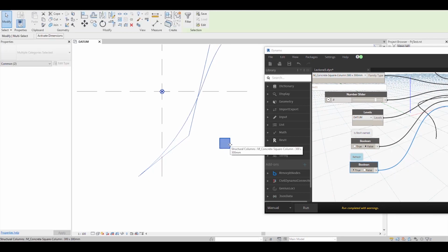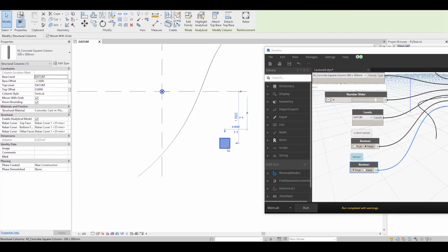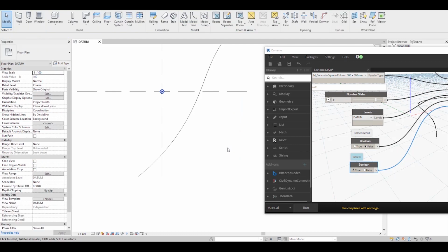When we load the object within the document and the object has never been placed within the workspace, the object is physically loaded into the model, but is not activated in the project, and that makes things a little bit easier in terms of performance, because we can load hundreds of families, but until we use the family once in the model, that family just stays there, not active.